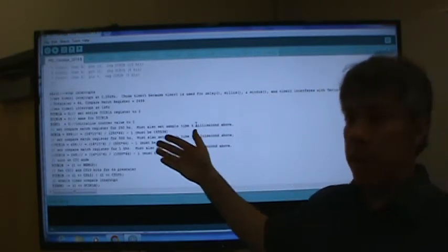So I had to play around with how often I computed, and I even did some work, here I'll show you that part. I even did some work trying to measure how much time each part of my interrupt subroutine takes, the part that's time-based, doing the PID calculation. I had to figure out how much time it took to do all of this, because this is quite a bit to do 1,000 times every second.